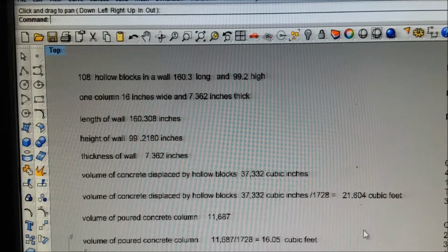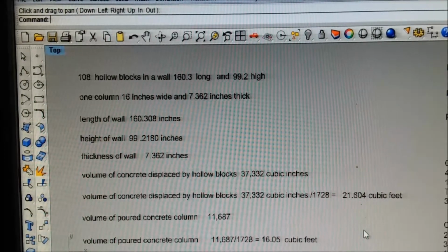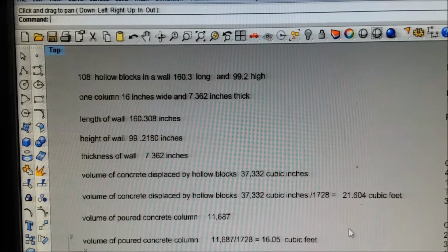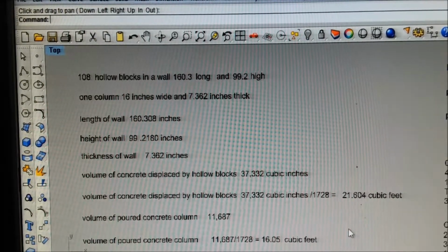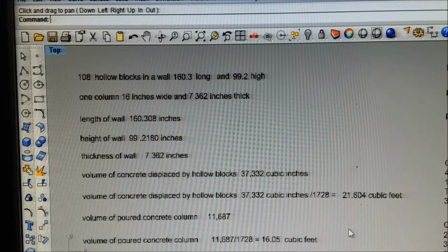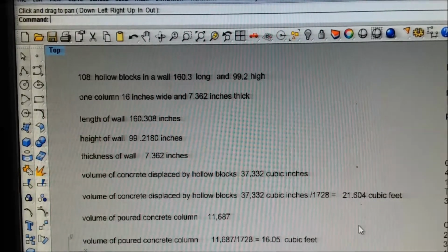I really don't see what adding another beam on top of a wall that's made out of exactly the same stuff really helps you at all. In our case, we poured a base beam, a wall with a window opening for sure, and sometimes a door opening too, and then a top beam. And we poured our top beam 14 inches wide, 24 tall.